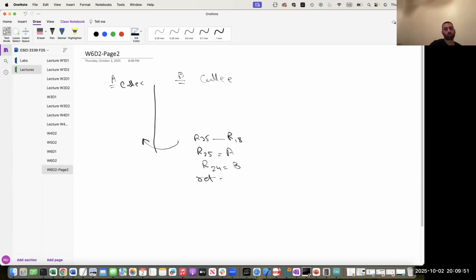Then you put the return instruction at the end. And then it will be the job of the caller to know that, if I want to get any return value from B, if I want a single value, I need to check the content of the R25 register. If I want two return values, A and B, I will read two registers, R25, R24, and so on. Okay.